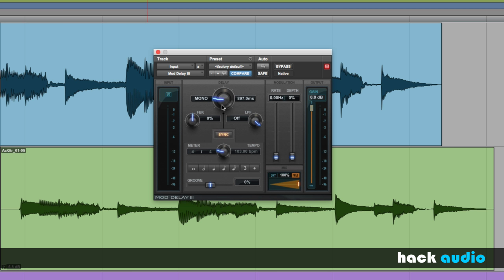So here, just like before, we're going to be able to shift the time delay in terms of seconds or milliseconds, but I want to have parallel processing. In this case, we'll change the relative amplitude of our dry signal compared to our wet by blending the two together here, down on the dry-wet meter. Then we can have a short time delay or a long time delay just by changing the number of milliseconds here.